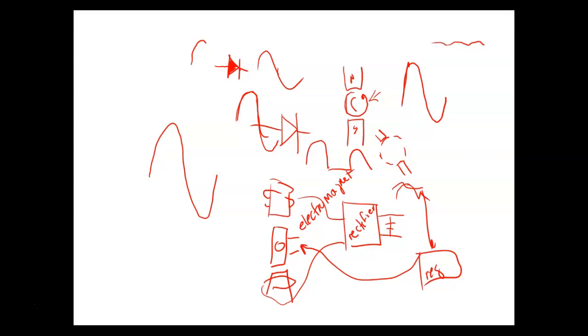So what we went to now is alternators. What advantage does an alternator have? Well, number one, it doesn't have to have that commutator. It's got to have brushes on it if it's an electromagnet. And we're not trying to take our power off a moving part.